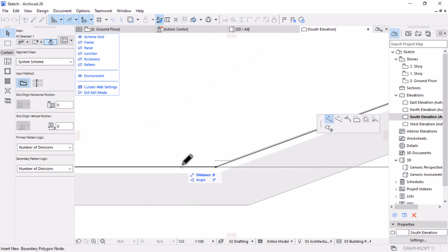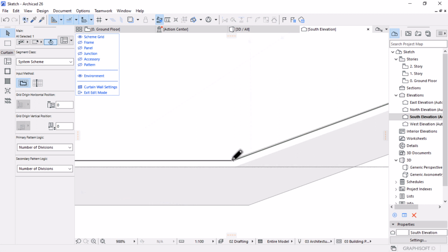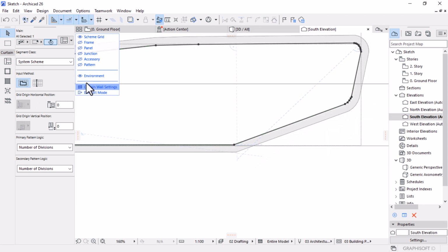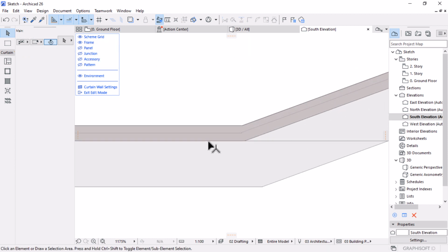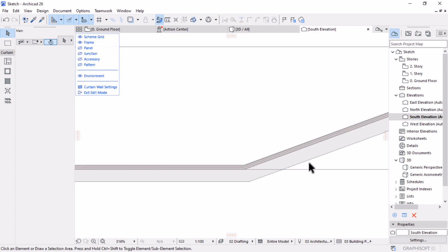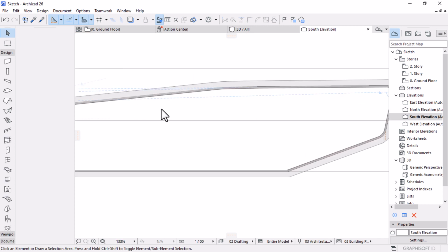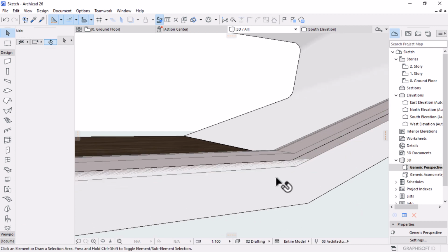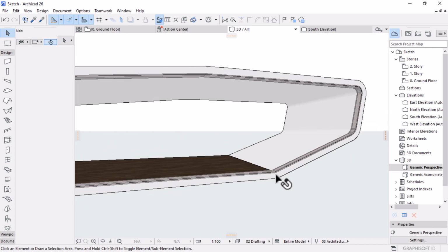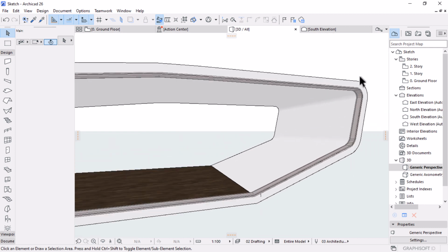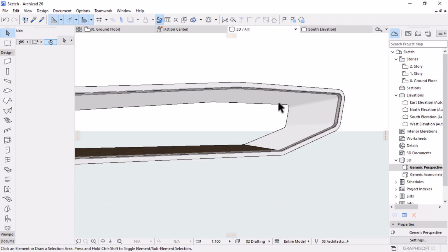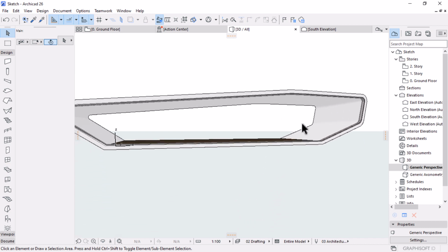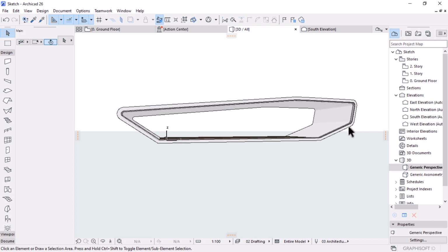And then I can now take this and offset the edge by 50. Okay, so if you activate your frame, now it sits right on the top of your slab. So if you hit exit, you could now see it on 3D. Perfect. Okay, we still have some material encroaching, but we can also fix that by using solid element operation to clean that. Okay, and then another thing is that we need to close off this.